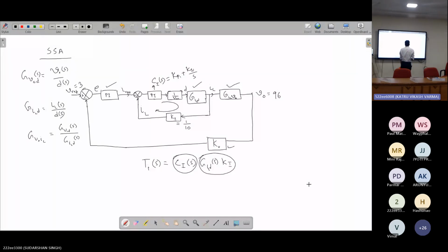What we have used is the closed loop bandwidth and phase margin specification to find the inner loop controller gains, the PI gains. So the uncompensated system has a bandwidth of approximately 5 kilohertz, with a phase margin of almost 90 degrees.